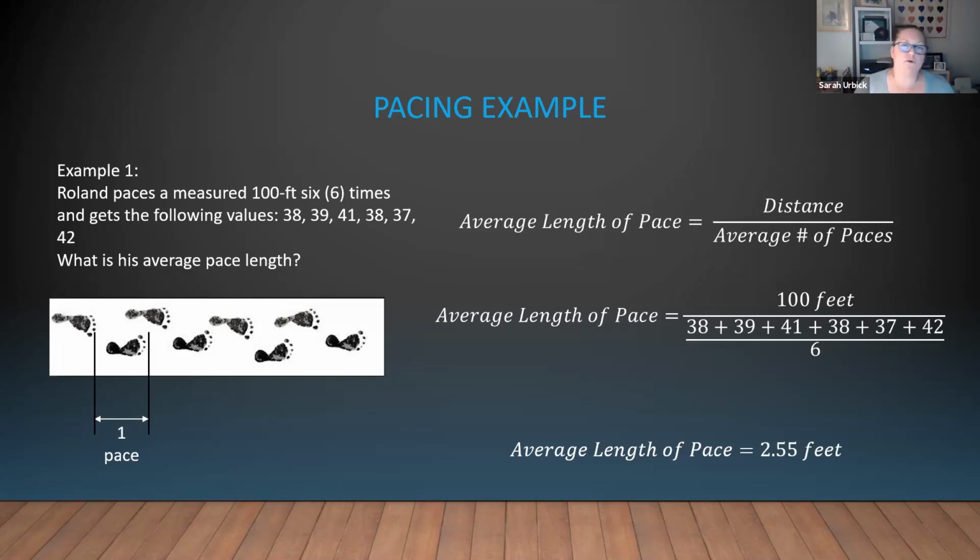The thing I always found to be difficult was trying to pace in uneven terrain. It's one thing if you're out on a sidewalk, on a street, or a football field, it's nice and flat, nice and level. But if you've got some little hills and some draws, it's a little harder to get that consistent, to get that accuracy of repeating your steps. So one thing to watch out for, maybe it's something that we need to correct for later on if we use pacing.